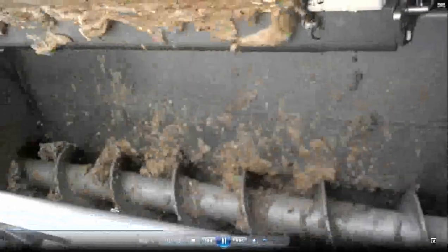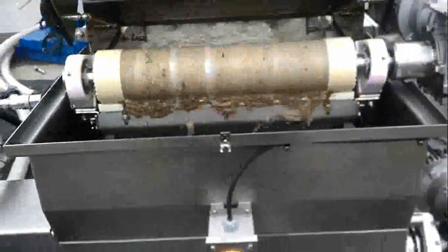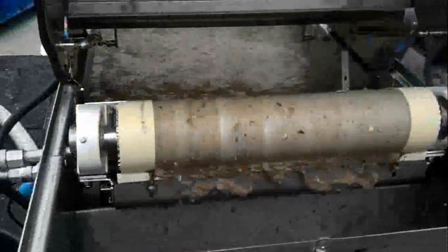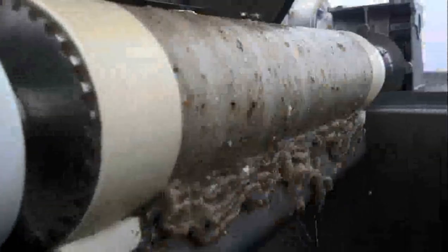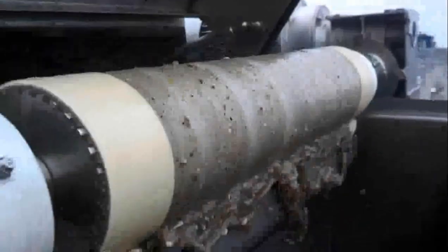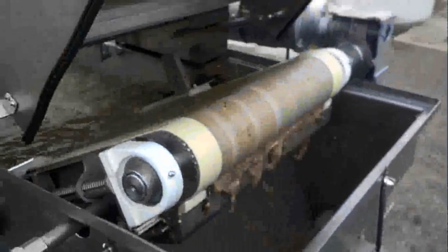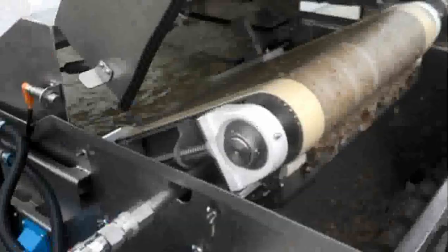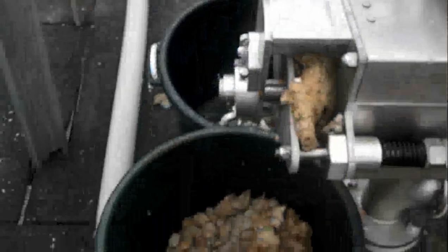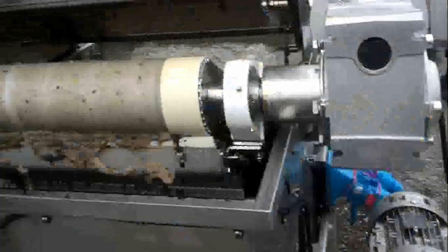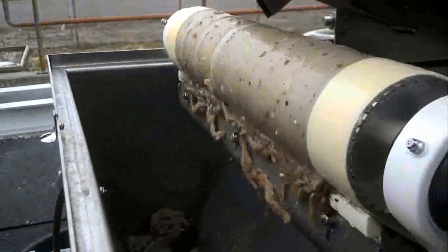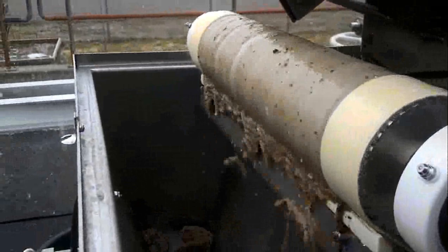But again, operating at capacity, you can see the level of capture that this system is capable of achieving. You have all of the sludge being collected, matted, and used subsequently as a filter to capture more solids, conveyed up and discharged into the sludge collection bin here. Now there's an integrated auger within this system here, which will begin to dewater the solids, which is an option for the canned stainless steel enclosed units. And this dewatering is very capable of very dry solids. That's roughly 35% dry solids there. So again, an EcoMat in operation at capacity on a municipal sewage plant.